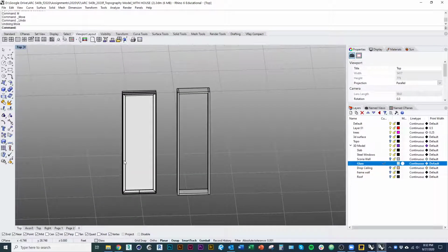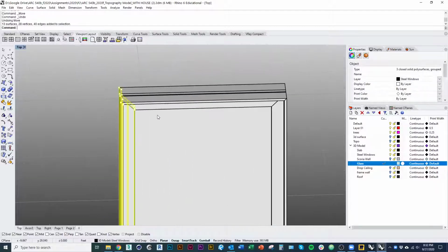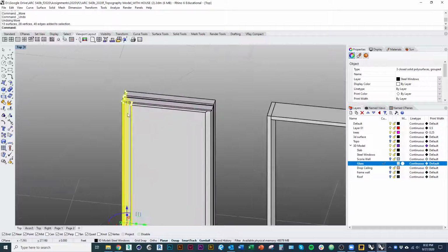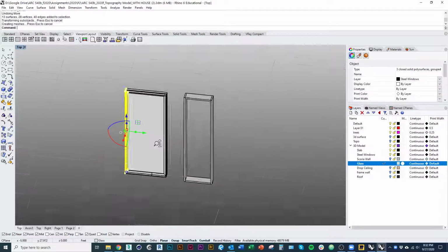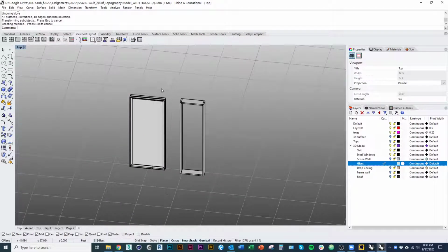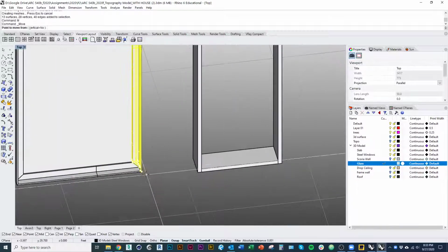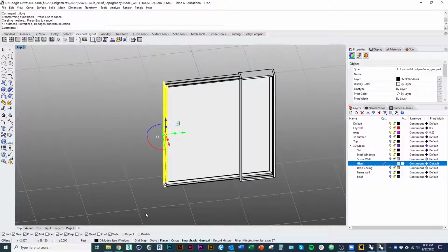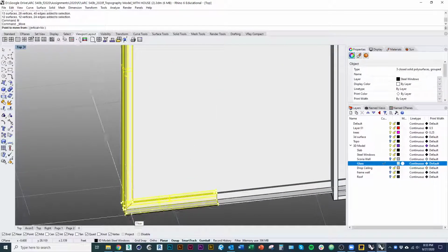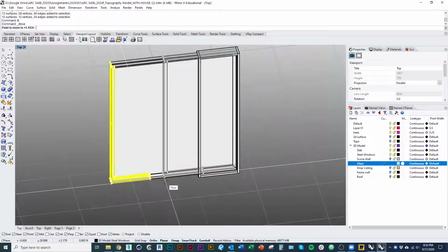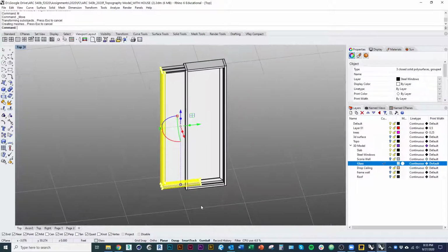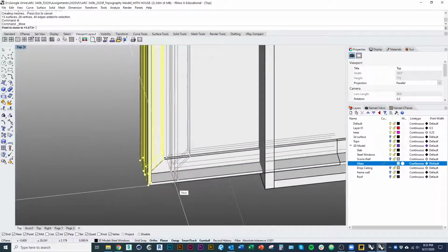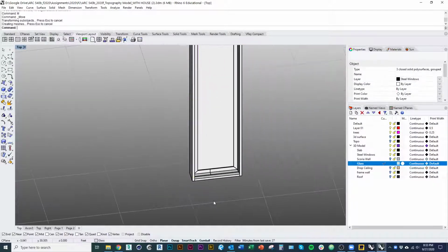Now there's an easier way actually to do this, which is if you hold Control-Shift on the keyboard and select, we can select the edges without even using the command. And that does exactly the same thing. And Tab does the same thing as direction constraint. Here's one area where you have to be kind of careful. Because there's an edge right there, we'd have to be mindful of that. Make sure it's moved in before we go ahead and start adjusting the rest of the panel.